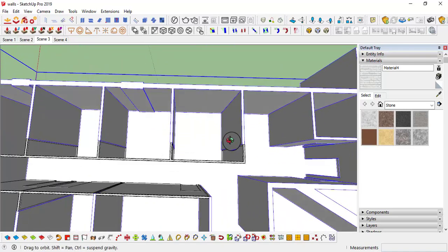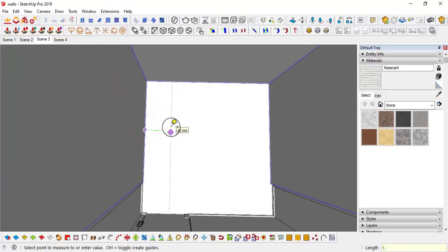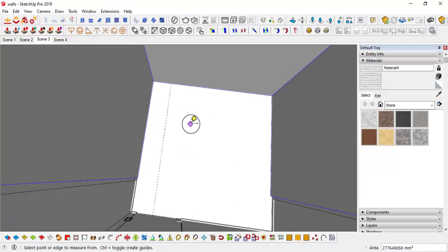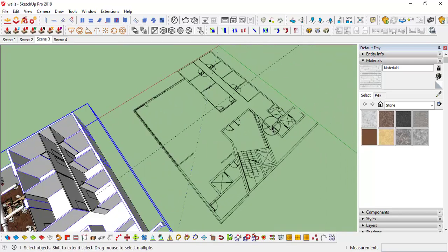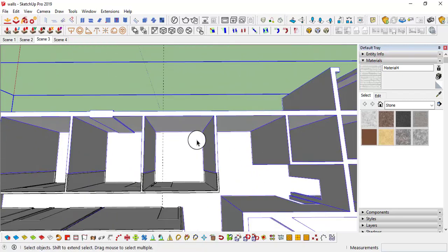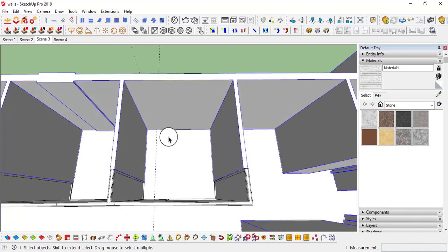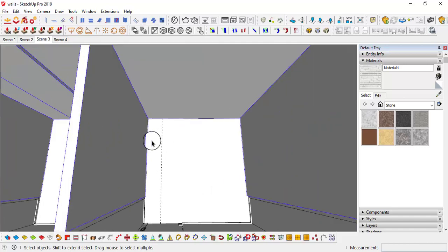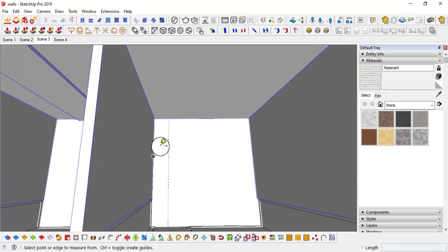So I was planning, let's start from here. I will take 1.5 feet. I am telling you again, the given drawing file is in metric units, but I'm used to imperial units like inches and feet, so that is why. But SketchUp has the ability to convert inches and feet in a single unit model, so no problem. Simply, if you are using imperial units in a metric model, you need to assign the symbols for feet and inches. You already know the symbols, right? So